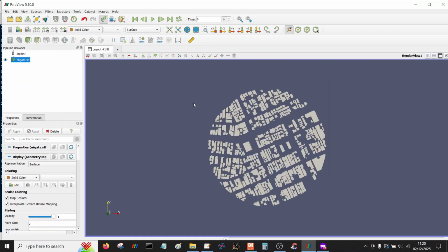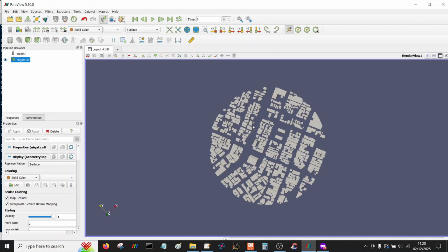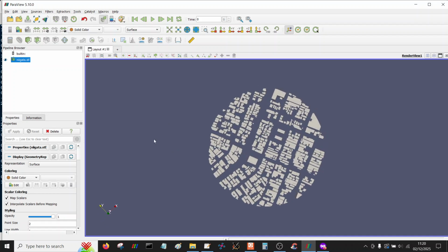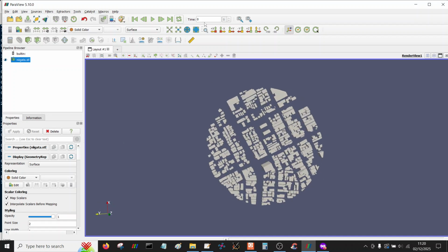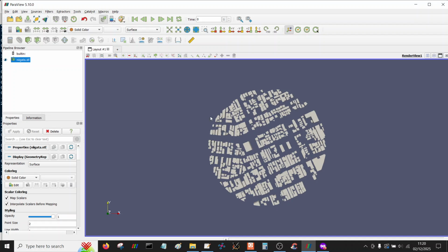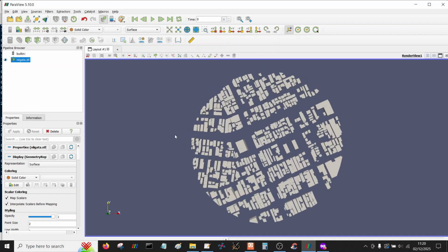I've just been validating against this one case, which happens to be the westerly wind direction, just purely because it's from left to right. So if I wanted to look at any other cases, I'd have to rotate the geometry a bit and then rerun it. So that's why I've just been running this one test case initially in the westerly direction.